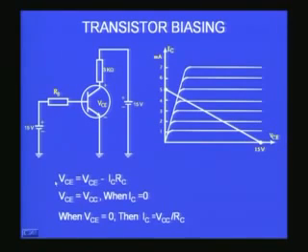So, now you can see there are two things that I can vary. For example, IC can change, VCE can change, and therefore this becomes an equation which corresponds to a straight line, and this straight line equation is called the load line, because that RC is the load which is connected in series with the transistor. So, these characteristics correspond to a particular load or resistor that I connect here. Therefore, this is called the DC load line, because it is now under DC condition. I have not applied any alternating voltage yet.